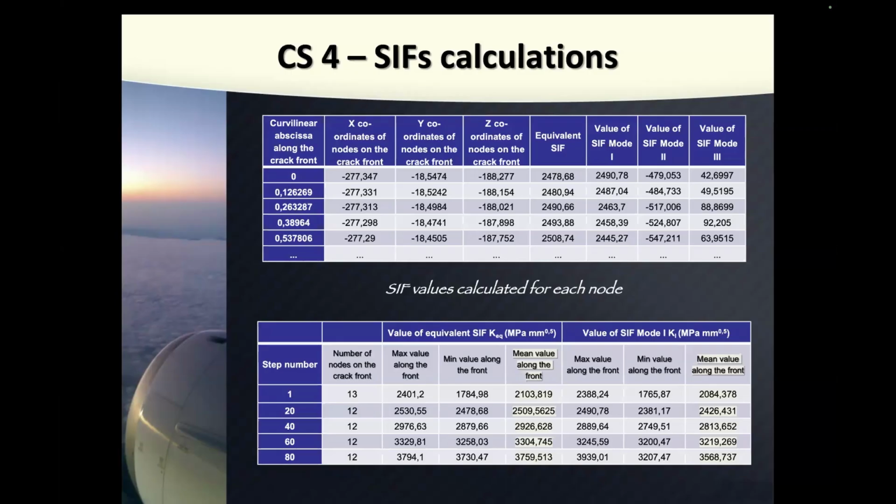So in ANSYS, you can also implement crack closure, but you must write Python code. It's not supported automatically. You cannot just click on some icon, something like that. Also, all other laws like NASGRO, Walker, Forman, you need to write a code. Only Paris is automatically supported, which means that you need to study the ANSYS code. The same thing for Abaqus.